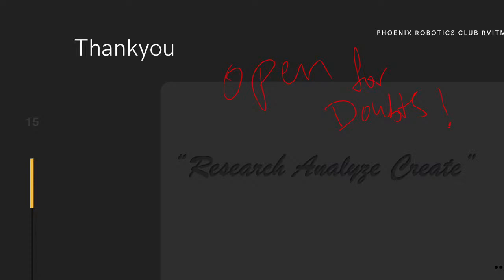I'm also part of the team for the line follow robot for the IIT Hyderabad Tech Fest. To make a line follow robot fast, you can use high RPM motors, but there are two problems. Problem one is the battery. If you use high RPM motors, they consume more power, so it will drain all your battery. That is the main thing.